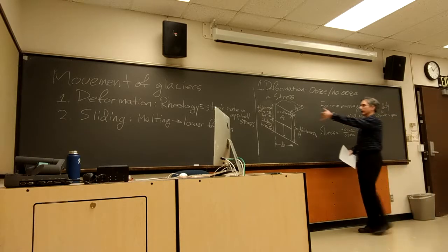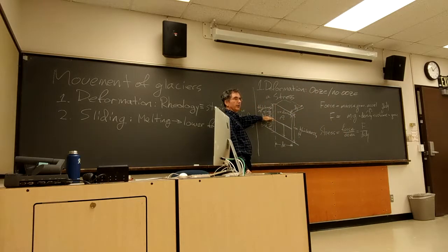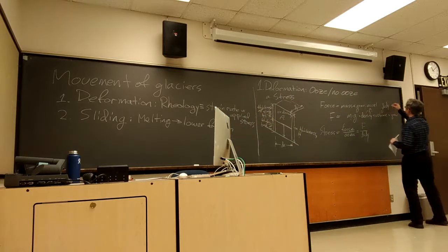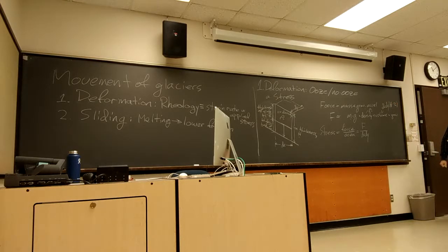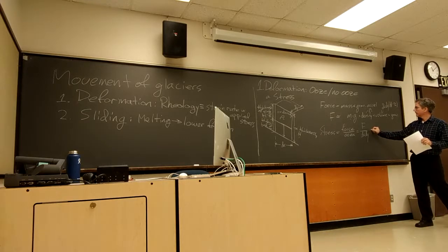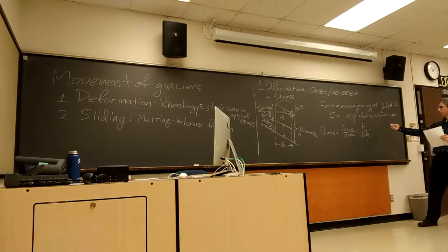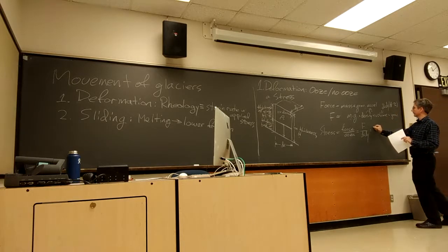And again, if we're just talking about this slab here, then we've got to multiply by the thickness, big H minus z. Okay. So all right, that means our total stress is going to be density times volume times gravity divided by area. So let's just write that all out.